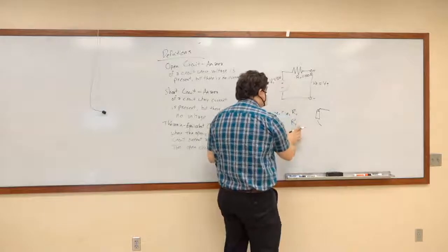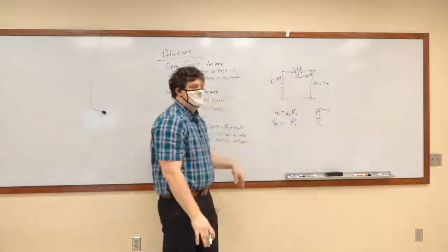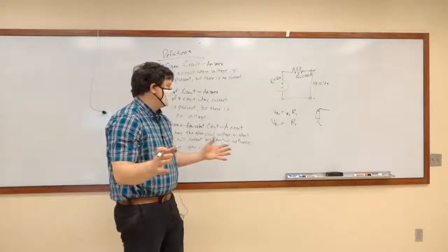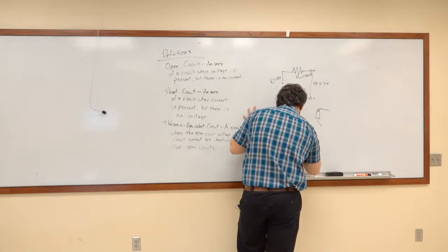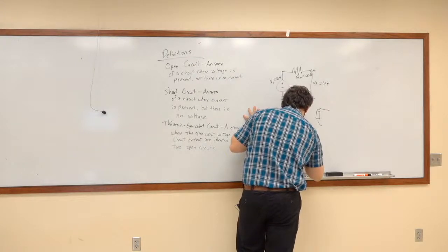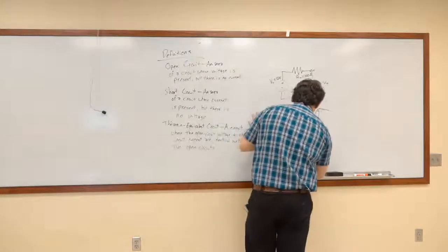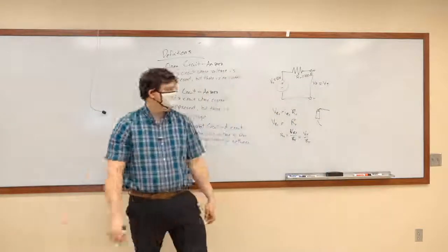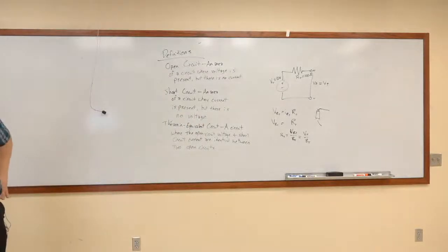We now know what the resistance is. We also know there's nowhere else in this circuit where there's a voltage applied, because this is a short circuit. We've short-circuited that terminal, which means that the current flowing through it is IRT equal to VRT over RT, which VRT for this system is just equal to VT. Okay? So now we know a few things.